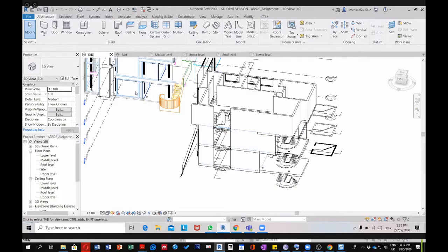2 meters, which means 2000 millimeters, and 1.17, centimeter or millimeter, like this. It depends. The naming is not that important, of course. I give it a name like this, and I can change now the parameters. As you can see, I have width and height. So the width 2 meters, because here it's in meter, not millimeter, and 1.17, and I click OK. So now I have a window with the dimensions that I have seen here.